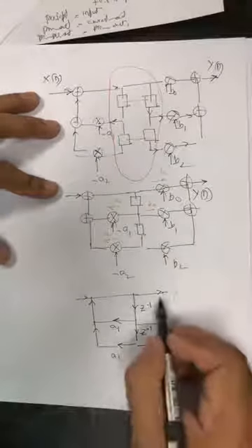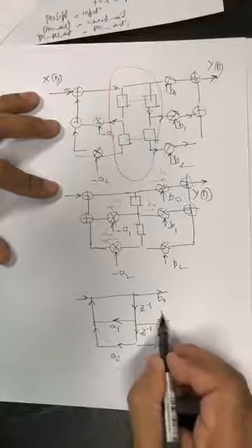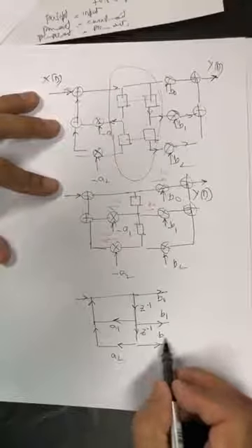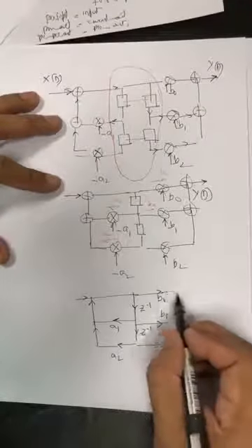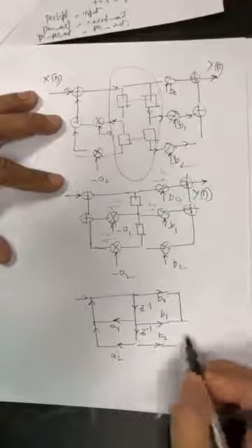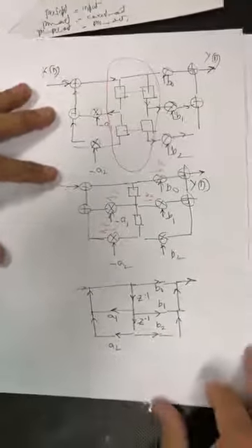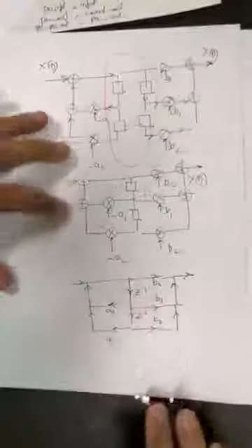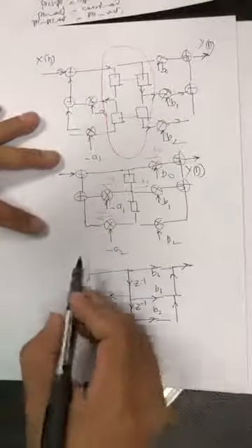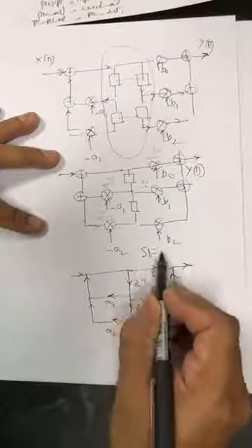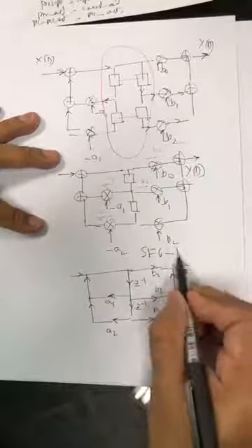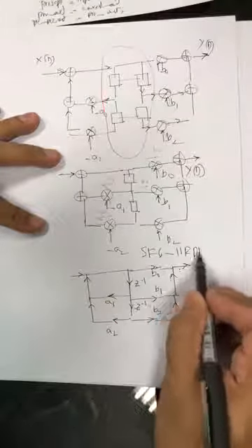So the book prefers us to draw a signal flow graph. So instead of drawing the boxes and the multipliers, just draw arrows, and wherever two arrows meet, it means an adder. We need not put an adder there. So this is our signal flow graph for IIR direct form 2.